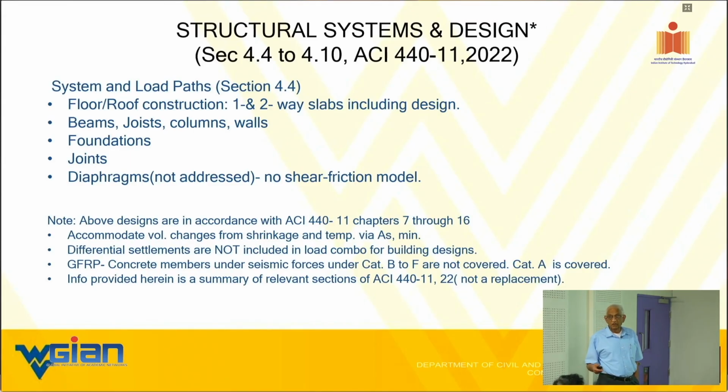You can easily get differential settlement if you are rehabilitating the ground, meaning you cut and fill, so you have to be very careful.